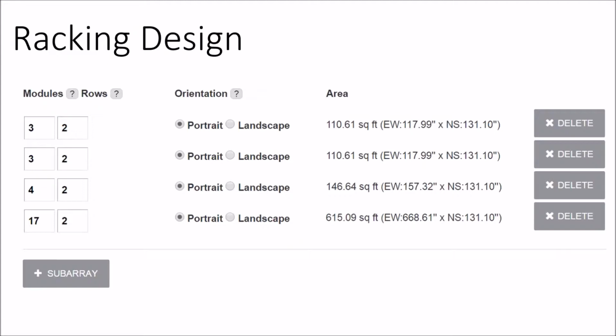Your racking companies also have sizing tools. And so when we look at how many attachment points, how many clips we have, what's the right size of the bolts so that the clip matches up with your module frame in an aesthetically pleasing fashion, you might say, well, do I have to do my array layout and then determine how many feet of rail I need and then look at their availability and say, okay, I need 8 sticks of rail, and so I need 6 splices for the rail, and then I have end clips for attaching the solar module to the rail on the end, and then I have mid clips that attach to the solar modules in the middle. How do I specify my racking balance of system material?